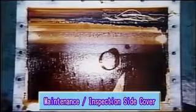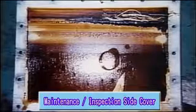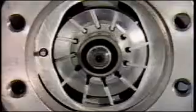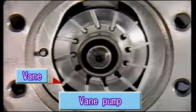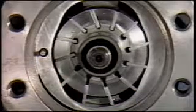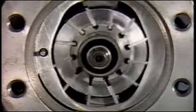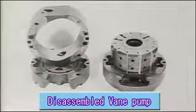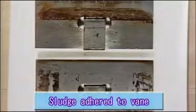By removing the maintenance inspection side cover, we can observe that brown sludge is completely adhering inside. The rotor rotates for the vane pump used here, causing reciprocating movement of the vane whereby oil is fed. By disassembling this pump, we learned that sludge acts like an adhesive, causing the vane to bond to the rotor, resulting in pump failure.